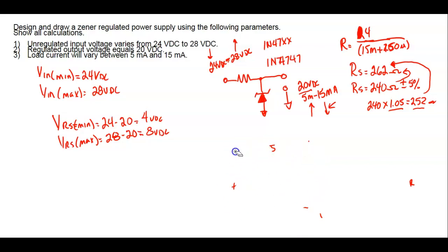Okay, so what's the next thing I need to know about my resistor? Yeah, the power rating on the resistor. So instead of trying to go through all these formulas, we know that I'm going to use what? I know the size of the resistor, and I know the maximum voltage it's going to drop. And that's when it's going to dissipate the power.